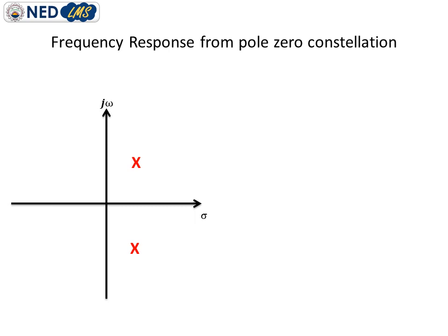However, we can also calculate the frequency response of this system. How? We have to move along the y-axis, and here we encounter a pole, so our frequency response will amplify and again normalize, and the second pole is encountered, so our frequency response will again amplify and reduce to the normalized value.